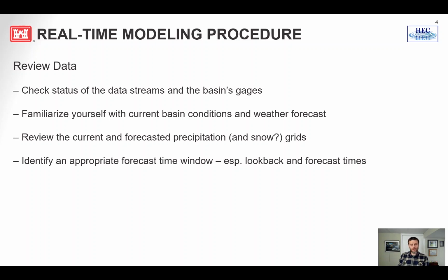And then also, as we've covered within the CABI itself, check the basin conditions. Understand what the basin conditions are. Is the condition wet? Is the weather going to bring more rainfall? Check the precipitation, whether it's going to be snow or liquid precipitation. These will help you understand what's going on in your reservoir system when you're operating it, when you're trying to figure out the system operations.